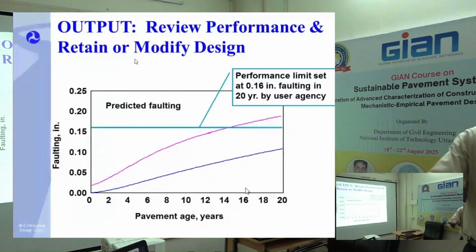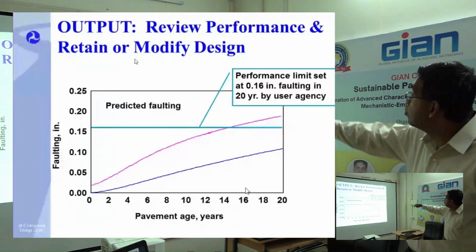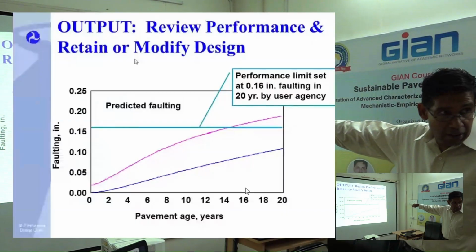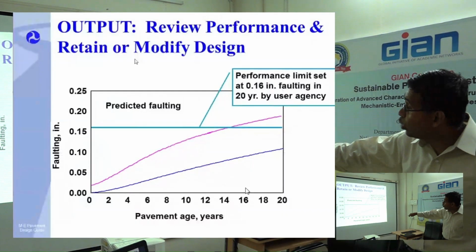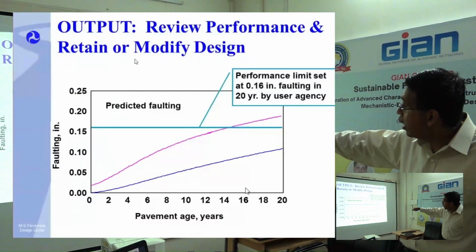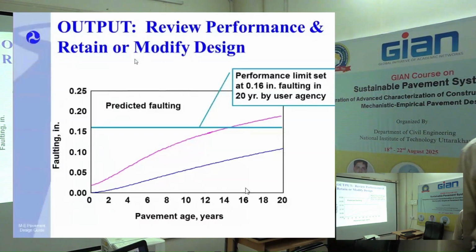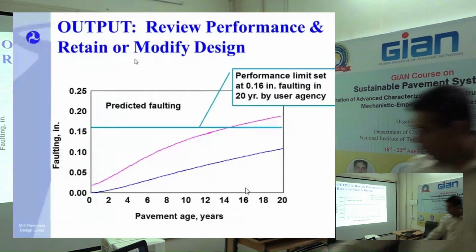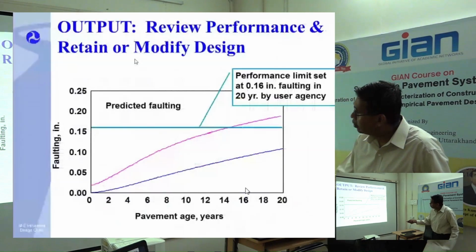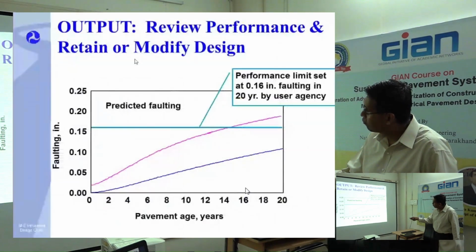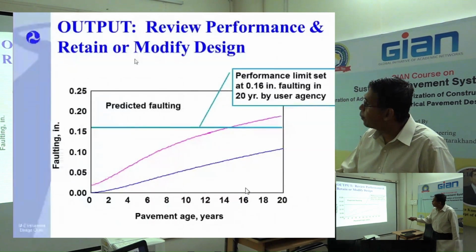Right? So if the difference in the slab is more than 0.16 inches, then it is unsafe. Everybody with me? Now, there are two numbers, one here and one here. I'm going to explain that. I'm going to make sure the slide doesn't cover it right here. This number below is at 50% reliability.